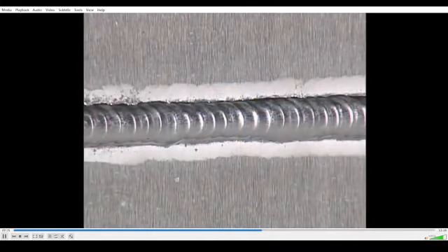With the right combination of balance and frequency, you can weld without continuous high frequency because the arc is so stable. And depending on the amplitude of the electrode positive portion of the cycle, you can weld with a tapered electrode. The end result is pinpoint precision and narrower heat-affected and cleaning zones compared to conventional square wave technology.